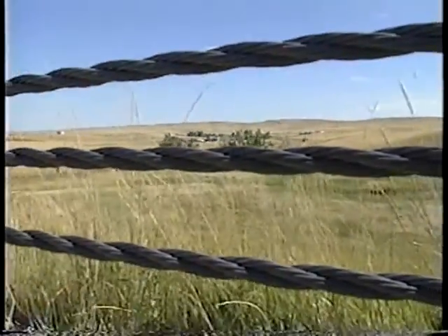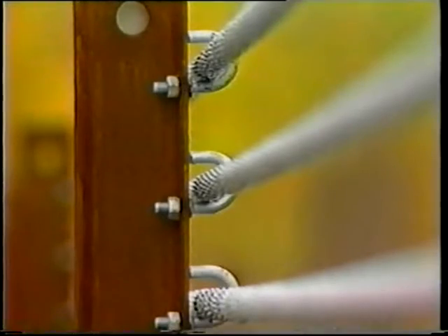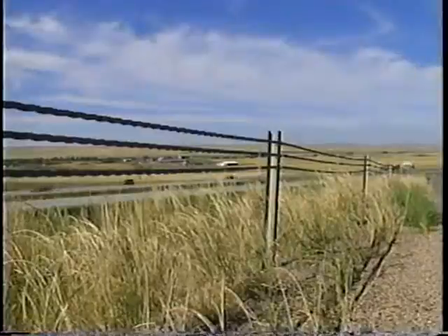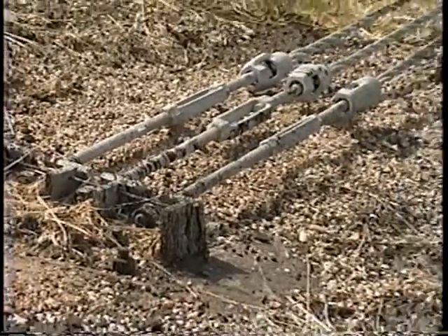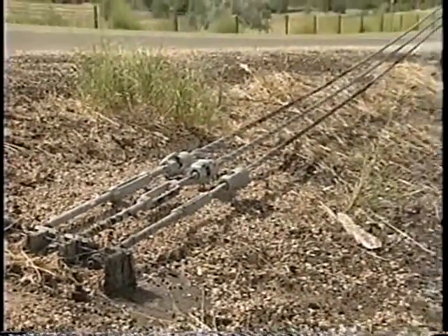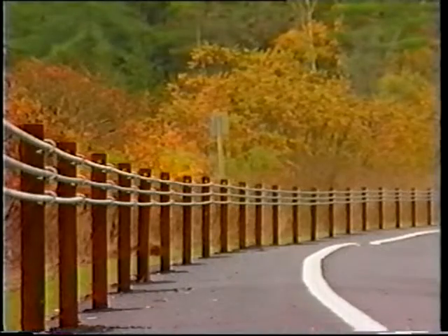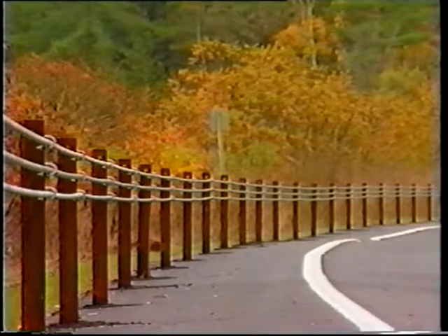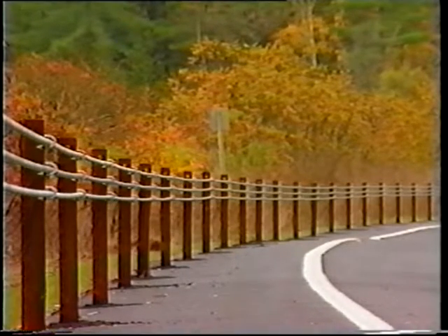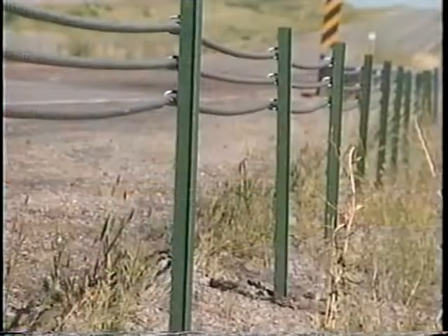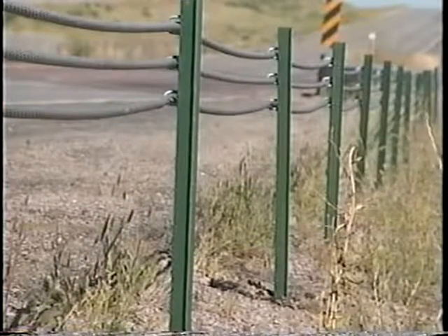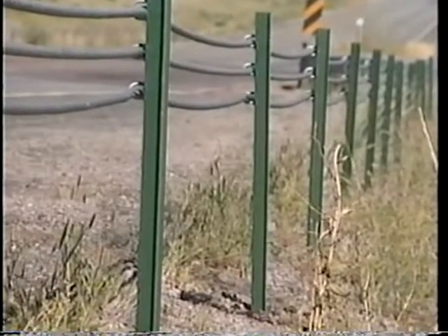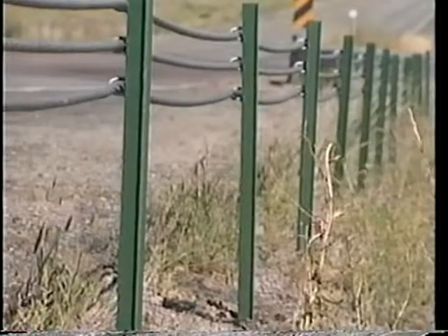The G1 consists of 3 cables, J-bolts for attaching the cables to the S3 by 5.7 steel posts, a concrete anchor, and hardware for attaching the cables to the anchor block. In recent years, several variations of the basic G1 guardrail have been developed that reduce the cost and enhance the performance of cable guardrails. The state of South Dakota has developed a cable guardrail that is similar to the G1 system, except that a smaller, less expensive post is used.